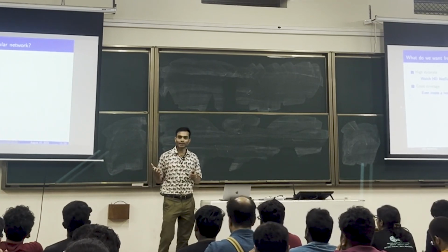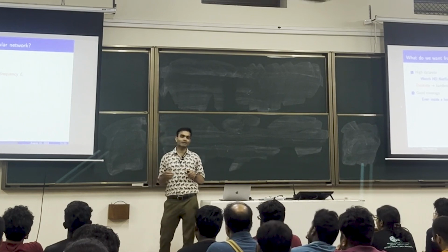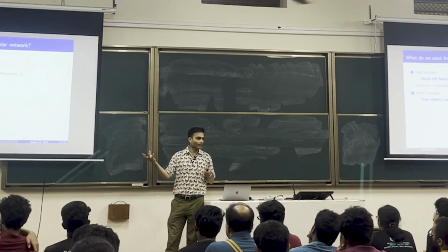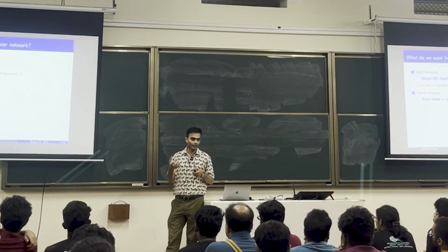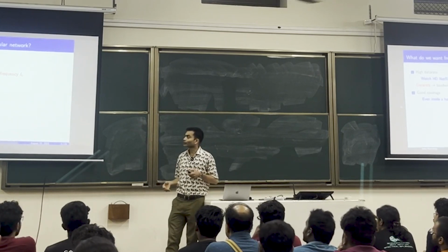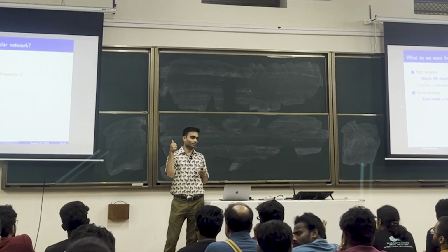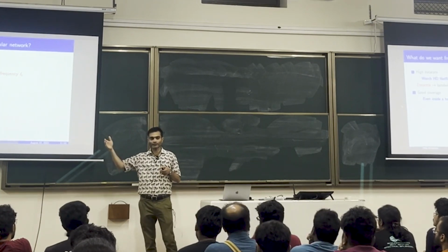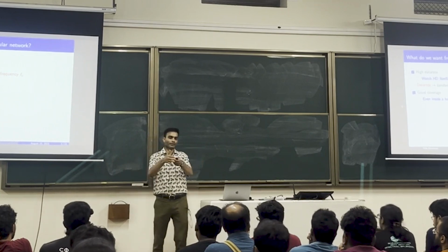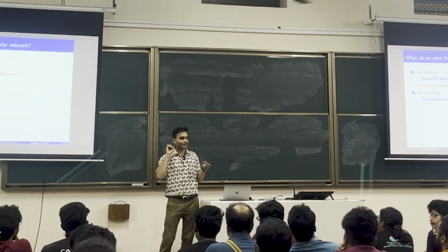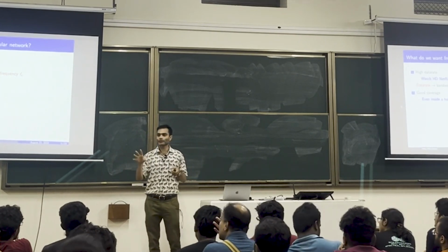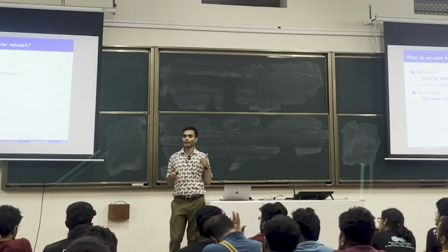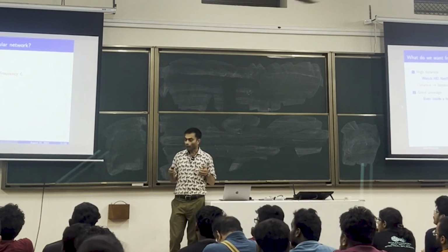So basic EE tells you that to increase the data rate, which is related to how much bandwidth is occupied by the mobile phone, by the base station, you need to increase the carrier frequency. This is one of the basic principles of communication systems. Higher the carrier frequency, I have more bandwidth. If I have more bandwidth, I can send more data. I can send HD video instead of SD video, things like that. Okay, so this is one of the requirements if I want more data rate, right? What about coverage?